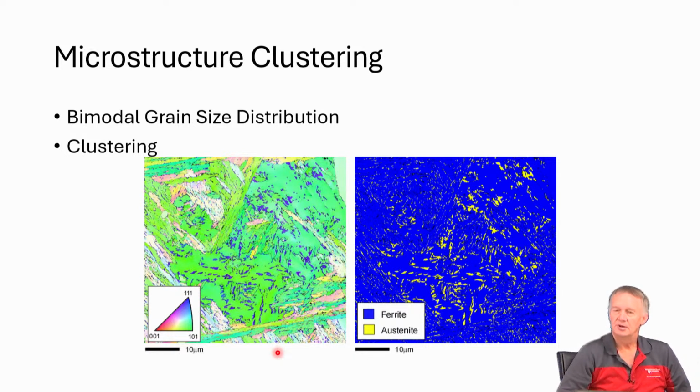Right. They both have 200 and 220 type bands in the patterns, but then they have two different ones as well, and that's what we rely on to distinguish between those two. If for some reason you're only getting diffraction from those specific bands, then it's going to be very difficult. If you have some kind of deformation where certain bands turn fuzzy, we're not going to have good diffraction along certain planes, which happens sometimes depending on the dislocation content, then